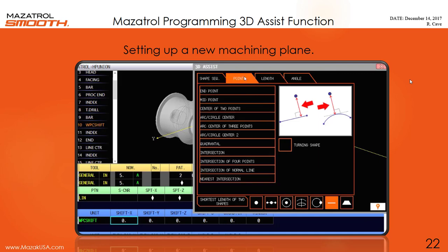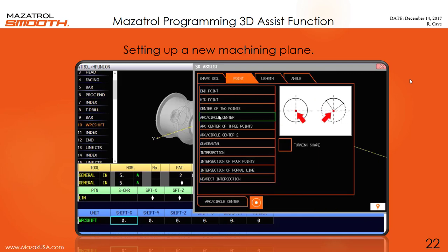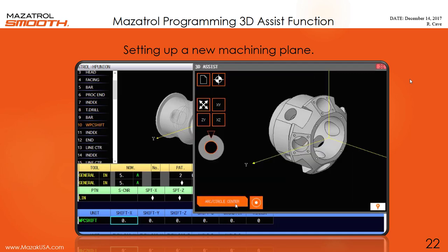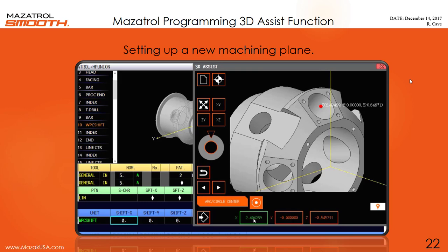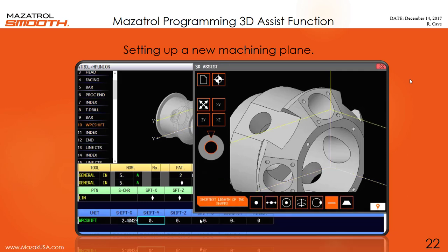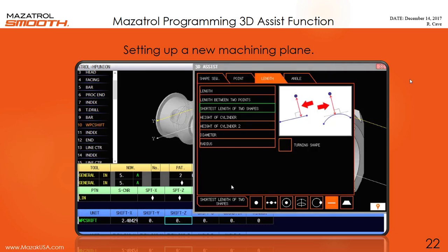This is all pretty easy in 3D Assist. All I need to do is choose the arc and circle center of this arc up here, select my X dimension, and have it automatically input to the Shift X. Repeat the procedure for my Shift Z, to move it in Z to the center of that hole.